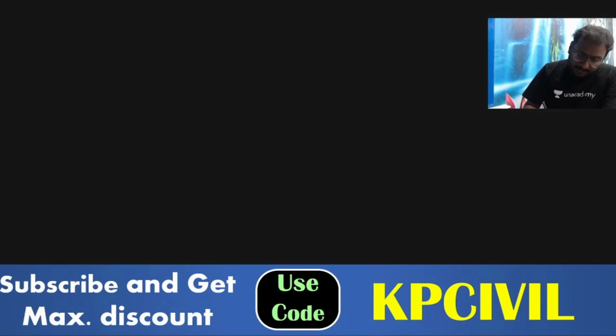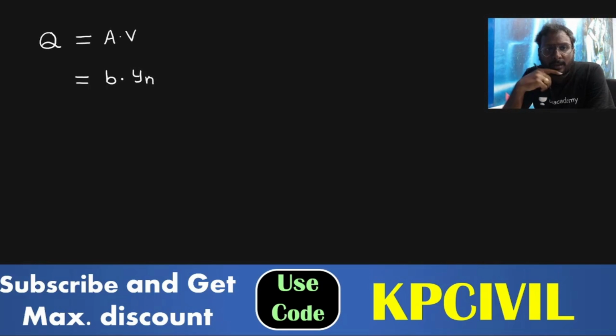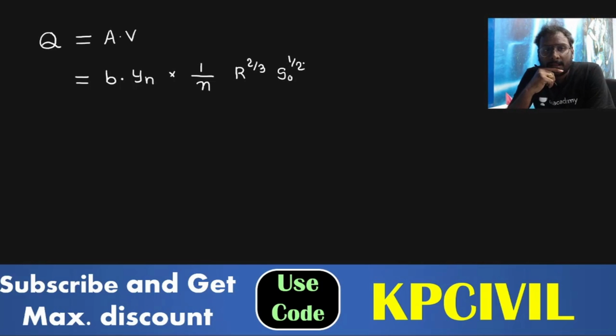To derive normal depth, use the continuity equation, Q is equal to A V. For area, I am writing B into Yn, width into normal depth. For velocity, I am using Manning's equation, 1 by n R power 2 by 3 S naught to the power 1 by 2. Q is equal to B into Yn into 1 by n R power 2 by 3 S to the power 1 by 2, velocity according to Manning's equation.